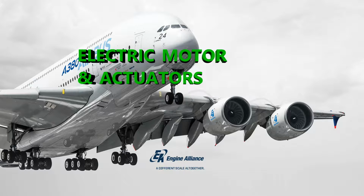All right, what about the stow position? Let's just say that the crew, the pilot, decides to not select the thrust reverser. Then what's going to happen? You've got that electrical thrust reverser actuation controller receiving that signal from the EIF, your engine interface function.